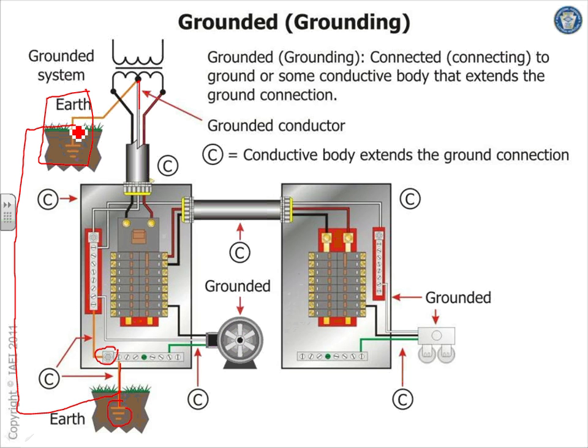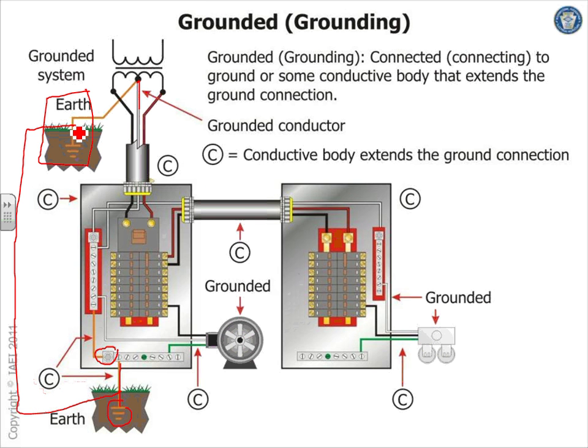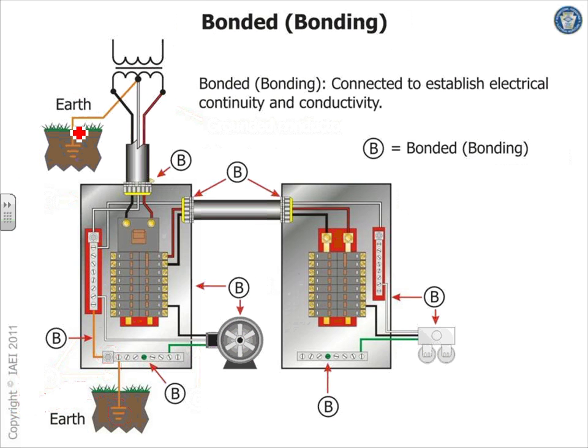Yes, it's not the best conductive method through the ground, but it's an alternative upon the loss of your neutral. It could be a safe alternative upon the loss of your neutral. Okay, so here's your grounding. You can see where the connection of your grounding is. Bonding, you can see bonding in the power system typically related, guys, to conduits and also bonding the equipment.